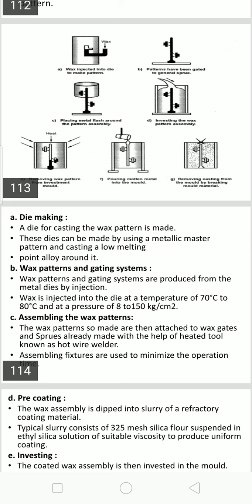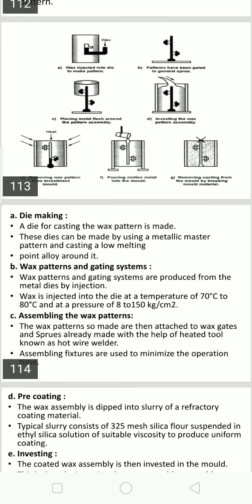The table is vibrated and the mixture settles by gravity around the assembly. In the fifth figure they have shown this. The whole table is filled with the investment mixture, fixed on the table, and the table is made to vibrate. This settles the sand. Then the investment is allowed to dry in air for about 8 hours.